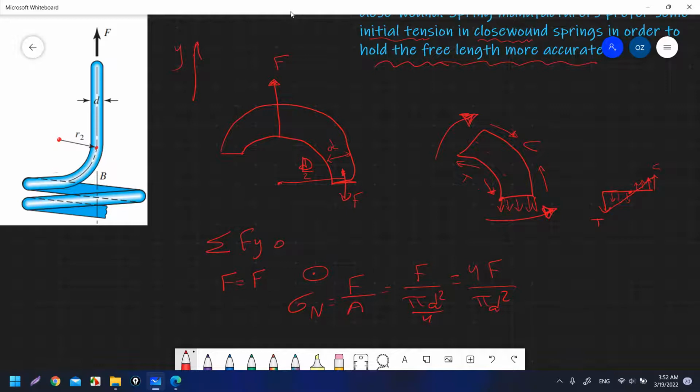But at the end you also have the normal stress, which is distributed uniformly over the whole cross-section area. On the right side, it is opposite to the compression bending stress, but here it is added to the tensile bending stress because they are in the same direction. So here you will have the maximum normal stress. This point is point A. That is why we call the force applied here F max.